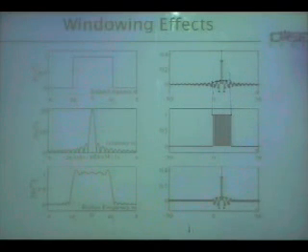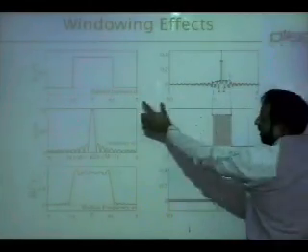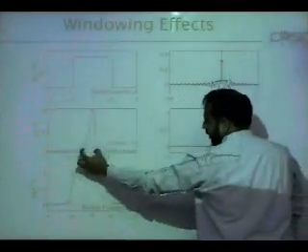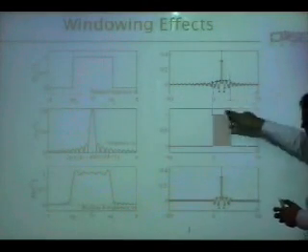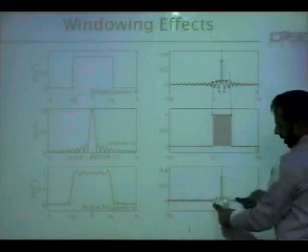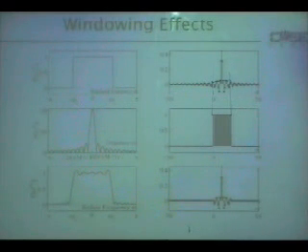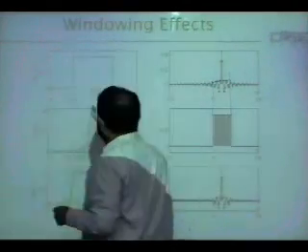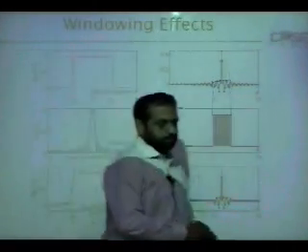Okay, you say this is in time. So in the time domain, the inverse Fourier transform of the frequency response is a sinc. Okay, the magnitude response. So this multiplication will result in a truncated filter which is realizable, which is an FIR filter. But this requires a convolution of this with this, and this convolution will cause, let's go to the next slide and we'll come back to this.